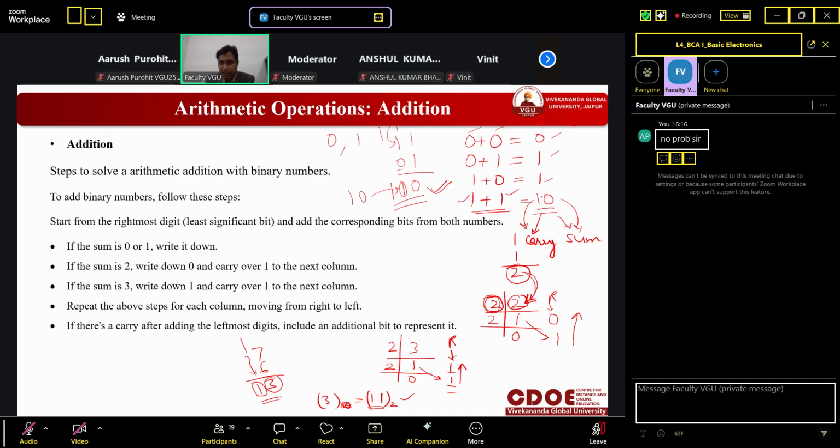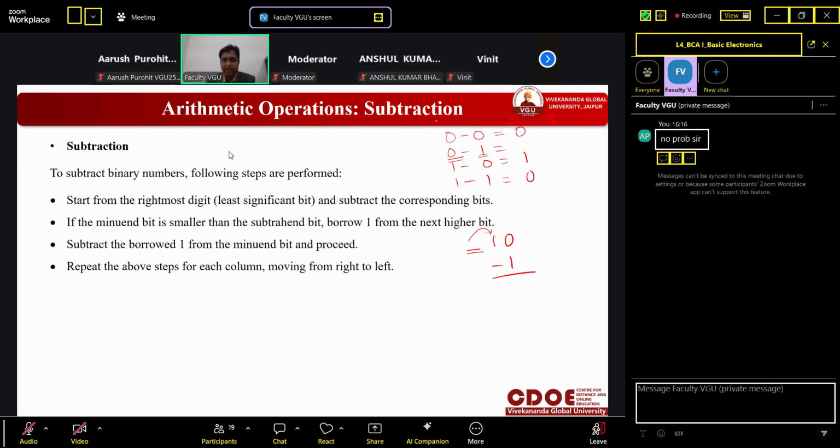And this is carry. So in place of writing like this, I will write 0 here at the sum side and carry 1. In all these cases, carry was 0 because there was no carry. Carry was in this last case only, 1 plus 1. So similarly, this S is subtraction, this is borrow. So in all these cases, this is 0, this is 1, this is 2. And in these cases, we have not taken any borrow. But here, you have to take borrow, this borrow. So I have written here, and this has become 1 0.